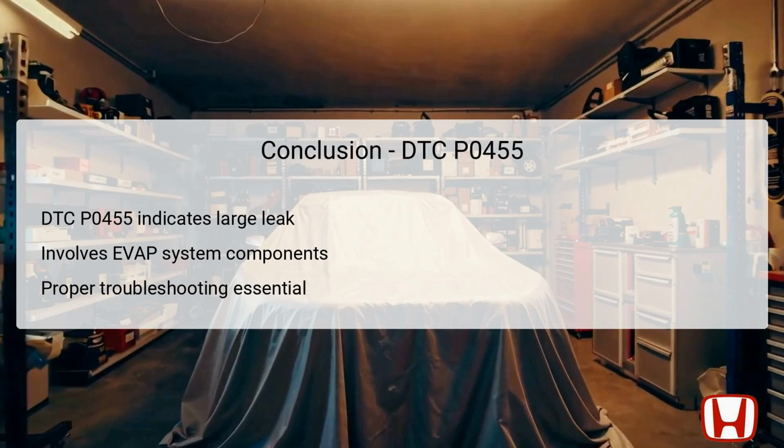Understanding the role of the EVAP components, such as the canister, purge valve, and FTP sensor, is fundamental for accurate diagnosis. Thorough testing and observation, including adhering to specific temperature and pressure conditions, form the backbone of the troubleshooting process. Regular maintenance checks can help avoid such issues in the future, ensuring the longevity and reliability of the vehicle. Properly addressing this DTC not only restores functionality, but also contributes to environmentally conscious driving practices.